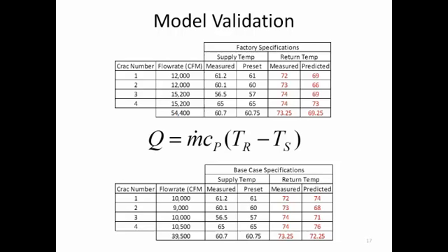So because there's mixing, it's hard to make an adjustment on one crack to try and make it come into line a little bit more. For example, if you look at your crack number 2, you can see that's the one that's probably the furthest off. However, if you made a further adjustment to the flow rate on crack 2, it might not make as much of a difference. It will make some difference there, but it might impact the others as well because they're all working together. That's right. So yeah, it's a complicated scenario.